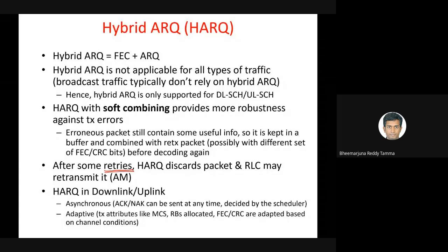That is what asynchronous means. Even in the uplink, when the handset is sending data to the base station, the base station can send acknowledgement to the handset at different time instances. Whereas in the case of LTE, it was synchronous in uplink and asynchronous in downlink. The acknowledgement coming from the base station to the user equipment would come after 3 milliseconds. That is not the case in 5G, where we use a configuration setting to modify when you can expect acknowledgements or negative acknowledgements from the receiver in both downlink and uplink.